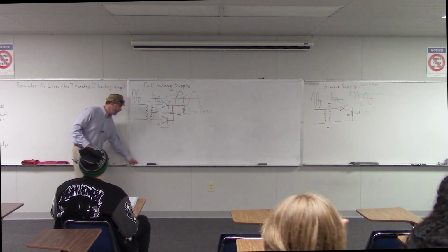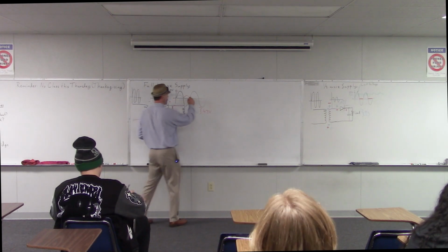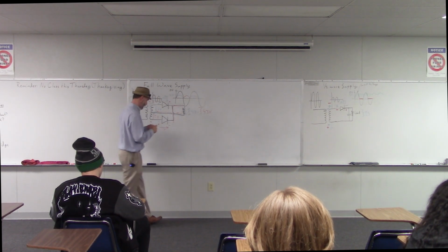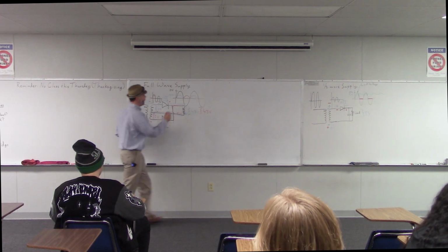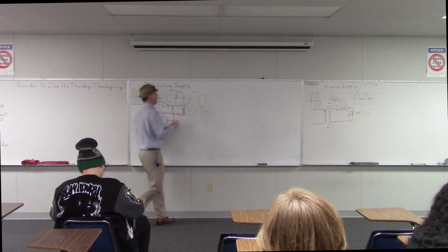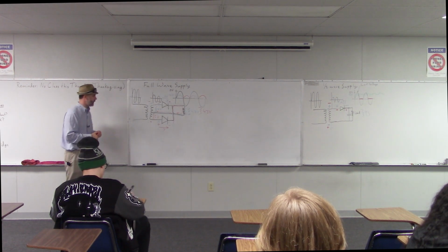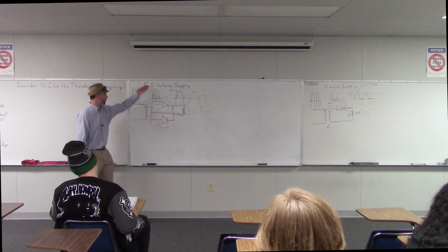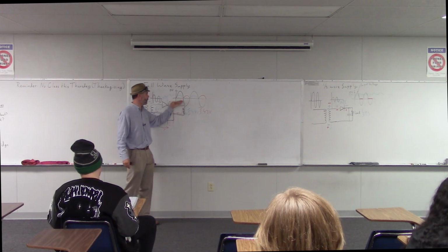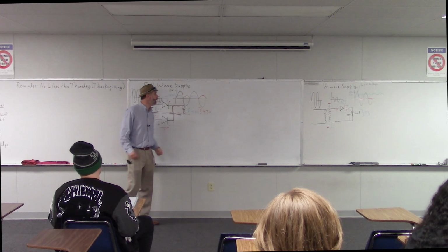So then we switch back to the original condition, and the output voltage goes positive again, and then we get back. And so this is what our output would look like. So you can see this is why we call this a full wave power supply. It captures the full incoming wave, both the positive part and the negative part.